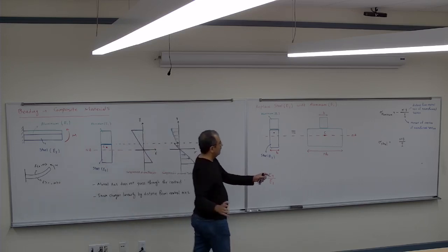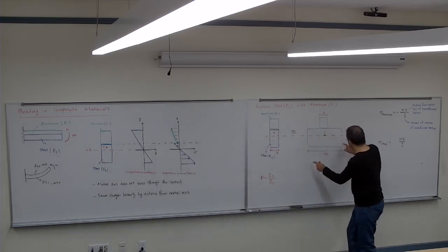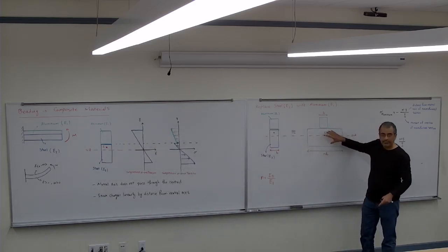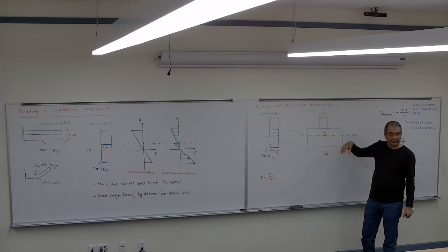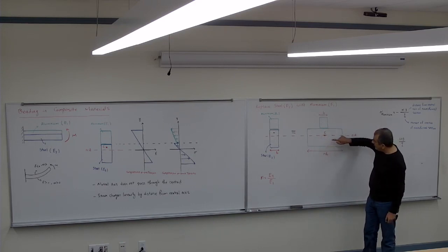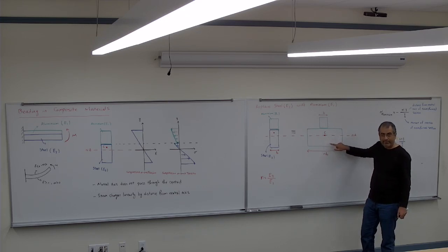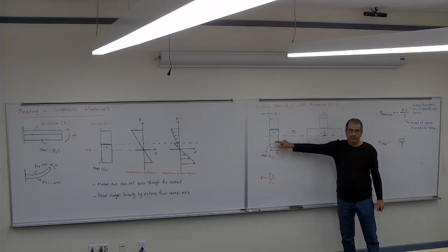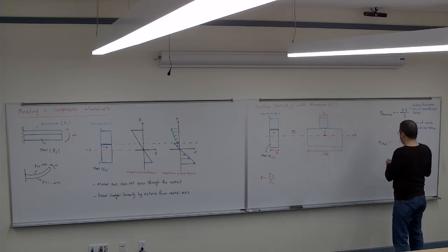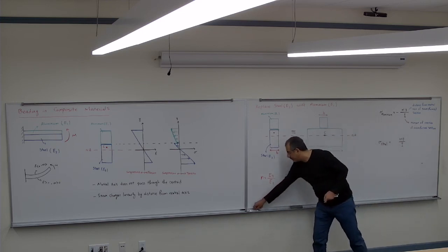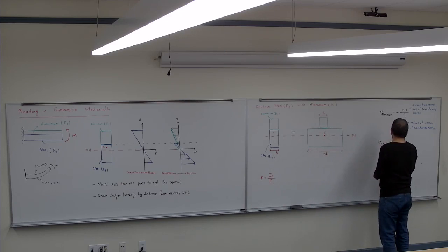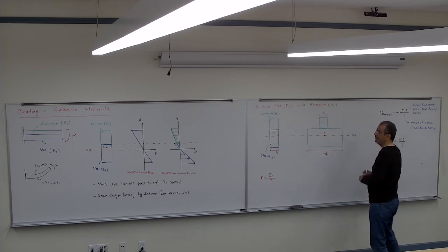So one more time, the tension in the transform part is gonna be n times smaller. So whatever tension I calculate here, I have to multiply it by n to get the original one. So it's gonna be n times My/I.